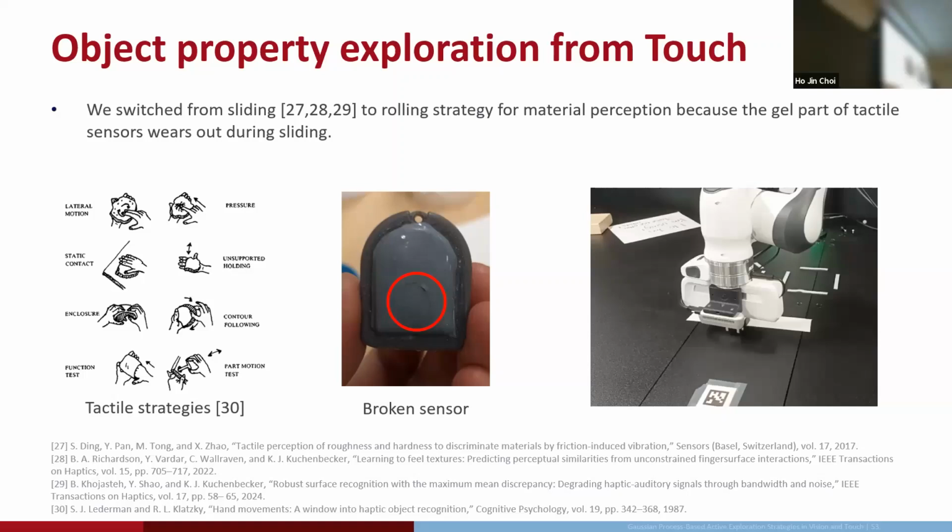Yeah, have you thought about, so you use the perception data to figure out what needs to be explored, and then use the tactile sensor on the shiny points to figure out the edges of it. Have you thought about using semantic information from the image to understand more about the material? For example, your rolling strategy or sliding strategy could be informed by knowing if the surface is rubbery or smooth.